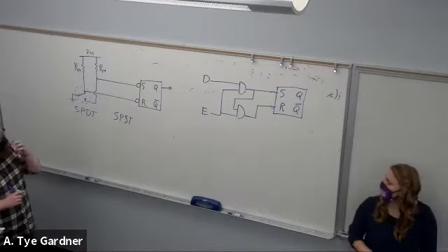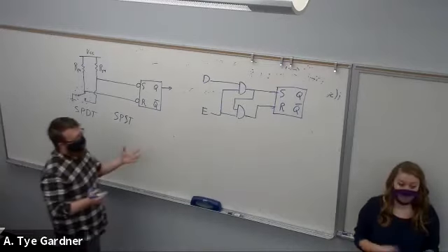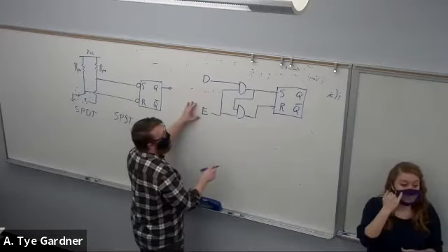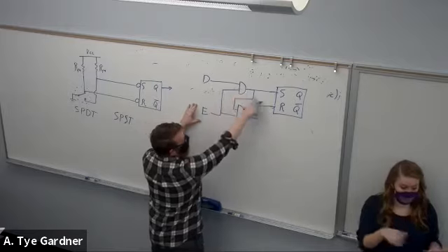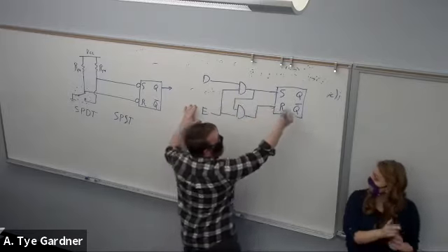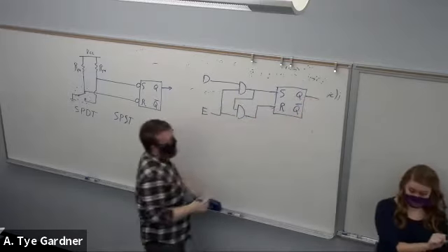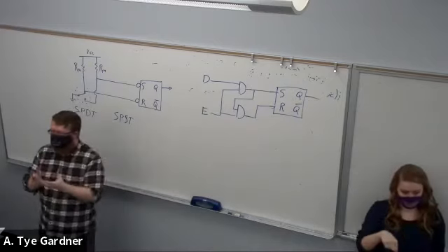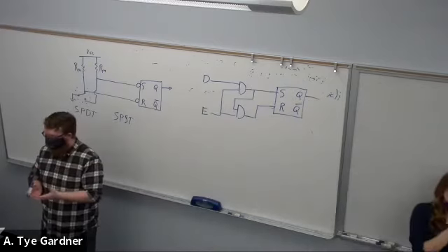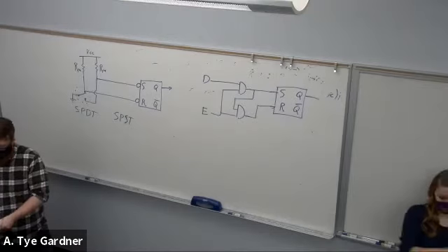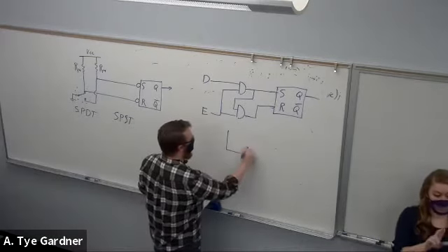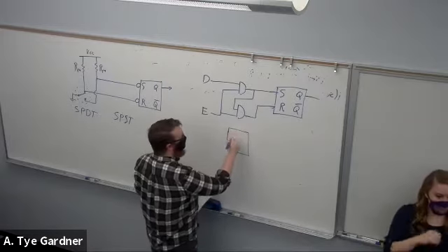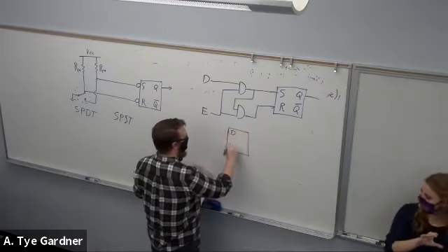And then let's look at what happens really. So let's say enable is on and we want to do something with D. D passes through to the set and that means we get Q of whatever D is. Just like the SR latch, if I were to create a schematic of that, it's going to just look like the following.